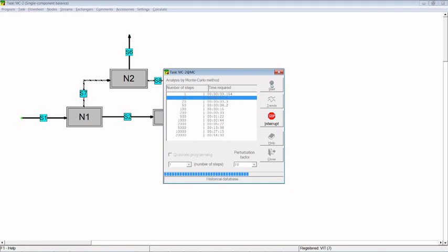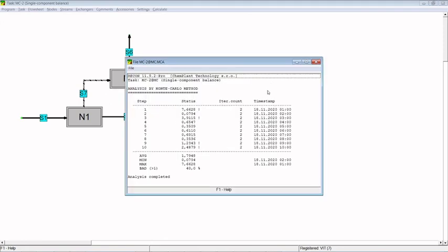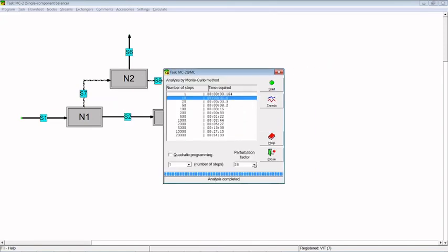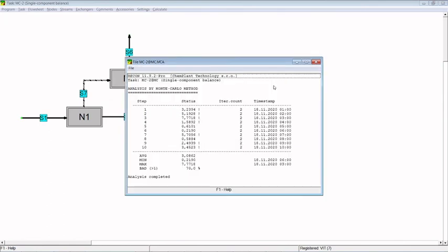In this case we can see 4 simulations, with status data quality above 1, marked by exclamation mark. The higher the generated random error will be, in Recon called perturbation factor, the more simulations with gross error will be. Using this simulation, we check the model robustness and tolerance to random error measurement during calculations, which can lead to divergence of calculation.